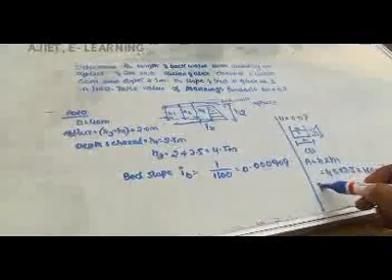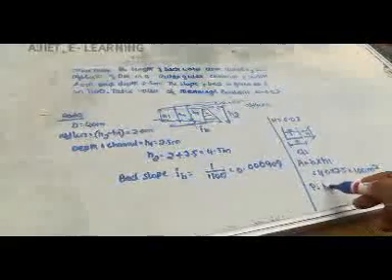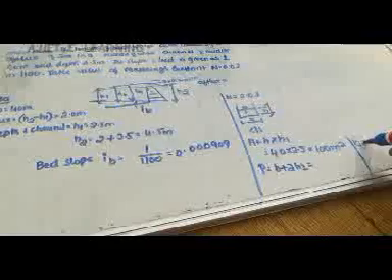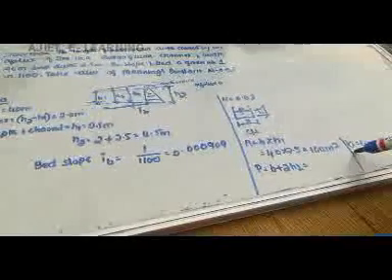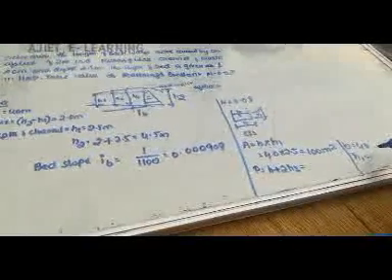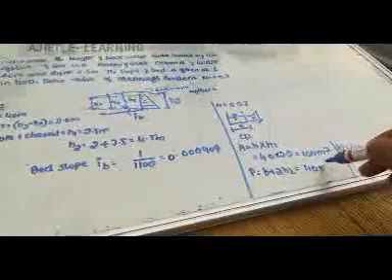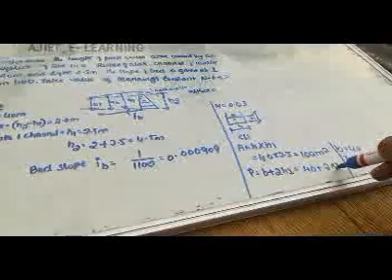And wetted perimeter P is equal to B plus 2H1. B is equal to 40 meter, and H1 is 2.5. So P is equal to 40 plus 2 into 2.5. So what is the answer? One sec, I will check the answer.